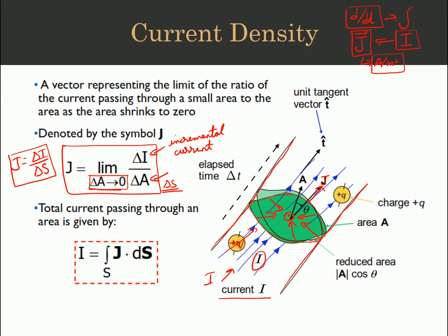Let us say I have this coordinate system, this is my y, this is x, and this is z, and this is an arbitrary surface S. If the current is moving in the upward direction, or we say it is perpendicular, and if we select a small region or surface over here, which is our small area, let's say delta A or sometimes delta S, then the output of the current from this area is represented as J, and you can see that the current density J is perpendicular to the surface, which means that the component of J will also be along a unit vector which is normal.